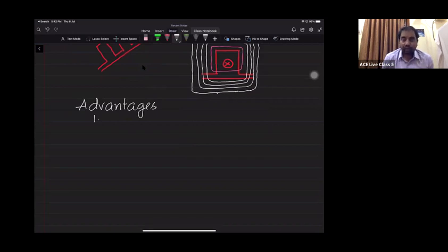In other words, the winding procedure with open slots is very simple and easy. Why? Because if you open the machine and look into the slots, you can see the complete opening of the slots, so placing the windings is not at all difficult.